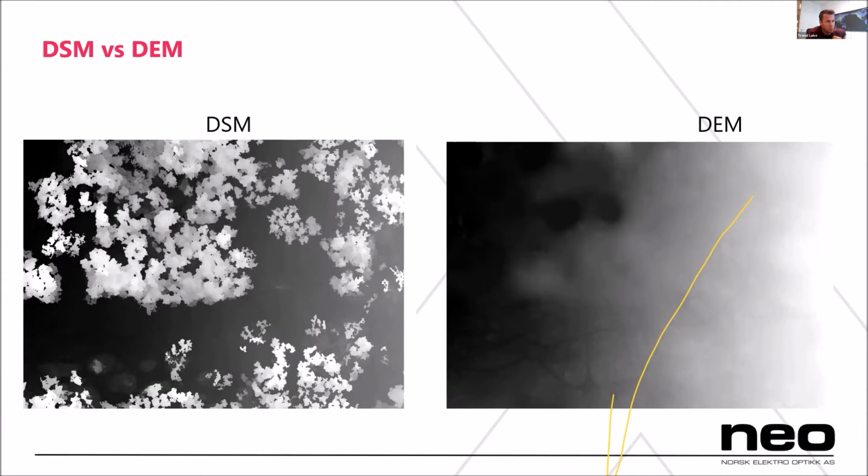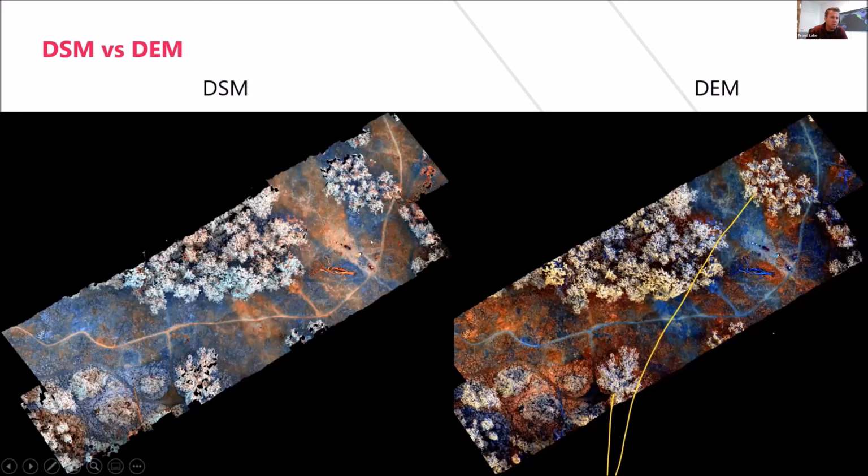And when you have to use the surface model, you need a lot better control of the boresight, and your navigation system has to be good, or else you will not have a LiDAR system and a hyperspectral system that's matching. And what's worse, you might be better off going back to the elevation model, because if this is not matching, it will be correcting for a tree where there is not a tree. So it will give you very wrong results. So that's important.